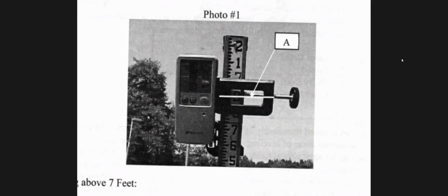So you can take readings real quickly with this receiver, because you're not taking the time to focus an instrument, to try to sight the rod, to find the rod. And if you had gone out with the level in the field the last 2 weeks, you would know that most of your time performing that lab outside is to get the instrument set up, get the instrument level, find the rod, focus the level, and then finally take a reading.